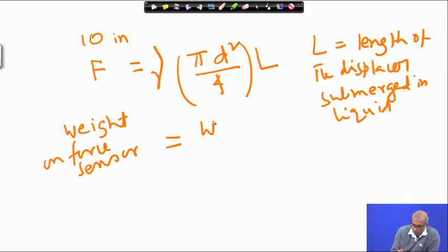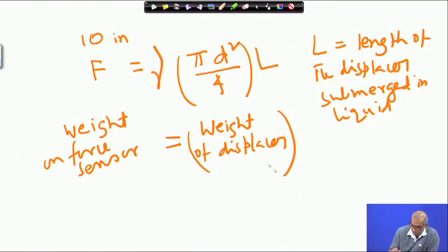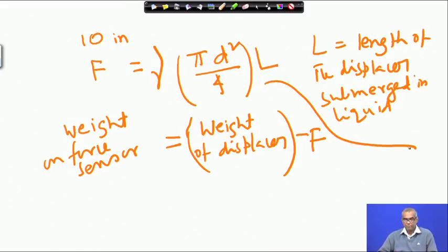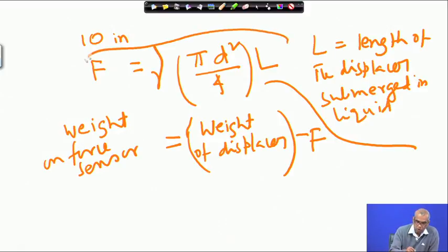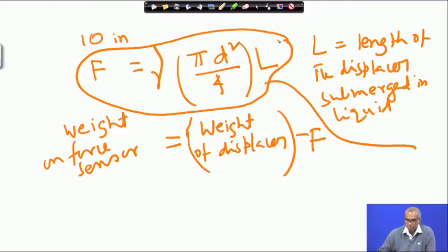That will be the weight of displacer minus this F. So, this is the buoyancy force that will be subtracted from the weight of the displacer. So, that is the weight, or the force, which the force sensor will sense.